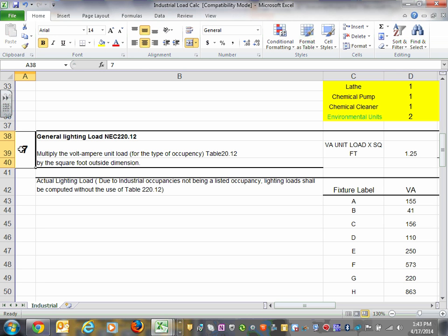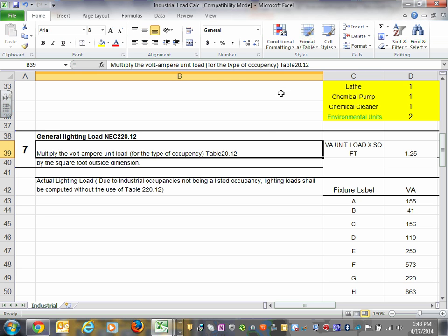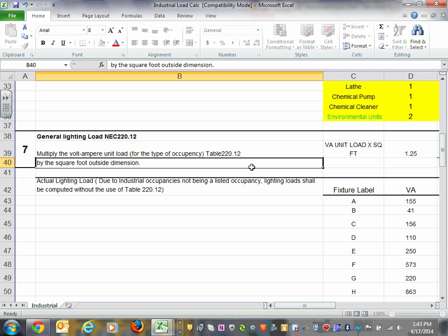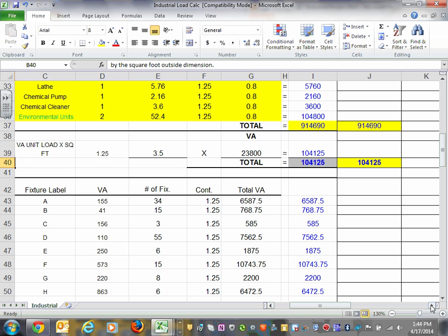General light. So we walk into any building, guys, and now we have a chunk of load for the receptacle. We need to allocate a chunk of load for, should be 220, isn't it? 220. Okay, so we need to allocate a chunk of load, guys, for the lights. Here's a couple of things for a commercial industrial building. For an office commercial building, the code says 3 volt amp per square foot across.